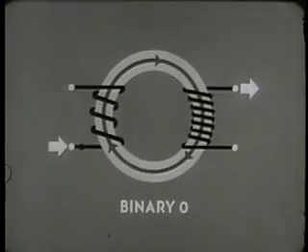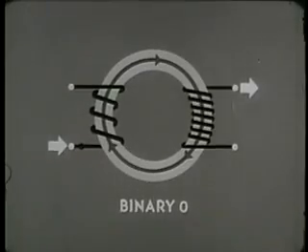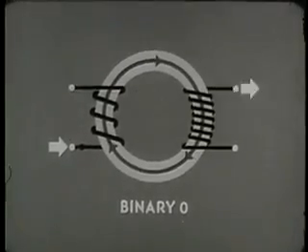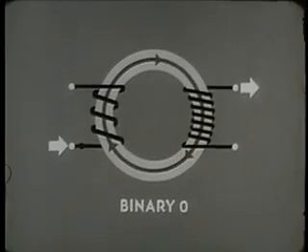The way these two conductors are wound, a pulse of current sent into the bottom of the input winding results in a pulse of current going out of the top of the output winding. We used a dot to keep track of the polarity of the input winding, and a similar dot will establish the polarity of the output winding. This gives us another rule about the dots in a magnetic core diagram. When dot current moves into the input winding, it causes the current to move out the dot side of the output winding, provided the input current produces a change in flux.